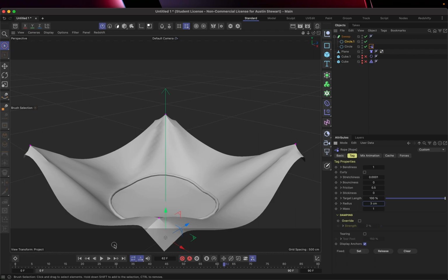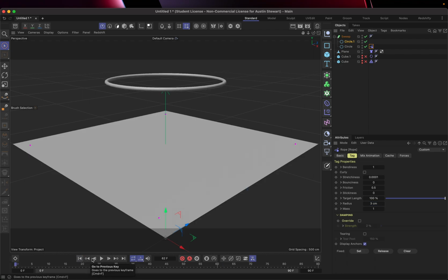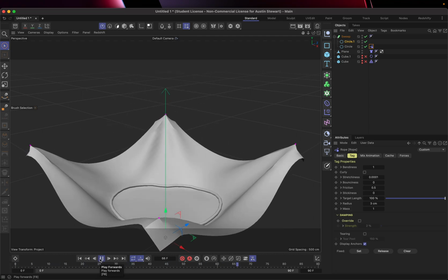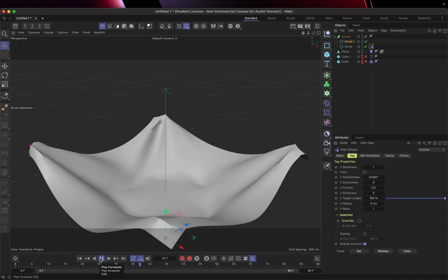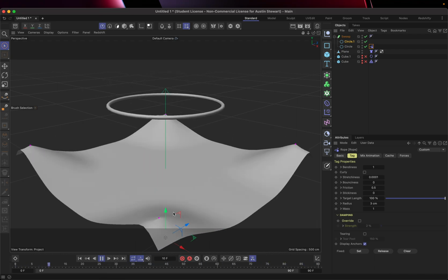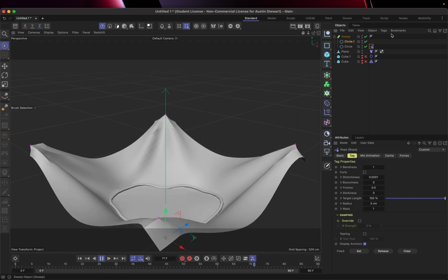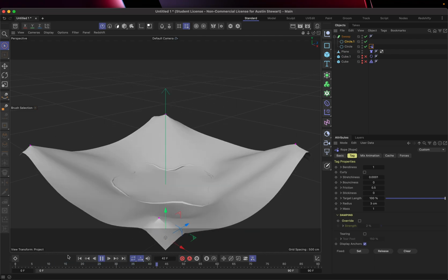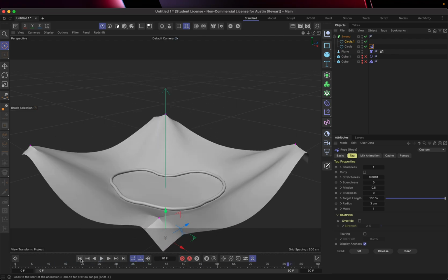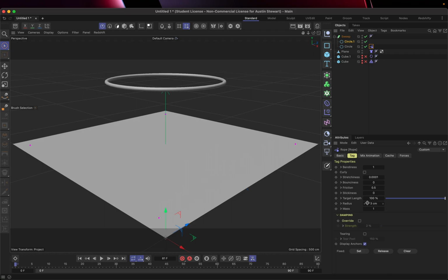So I'm going to set it to 3. I'm going to jump this back up. We're going to run this again. Right? It's still going through that surface a little bit, right? There's some collision issues there. Again, we could probably set the thickness on our cloth a little bit thicker as well, or we could increase the thickness here. And that's like the first step to resolving some of those issues.